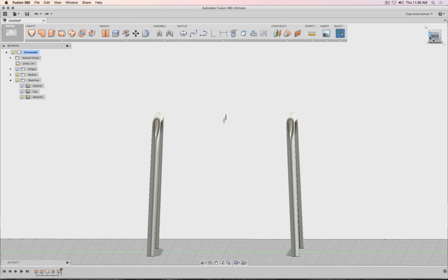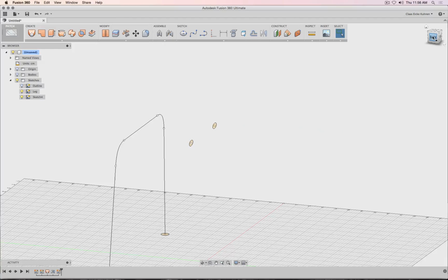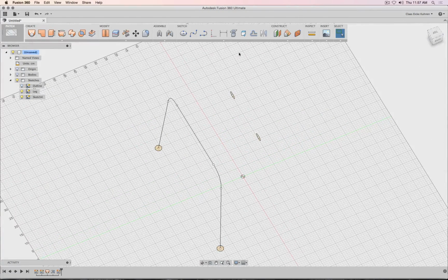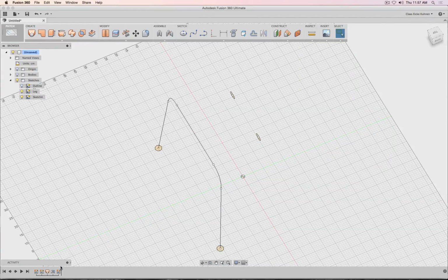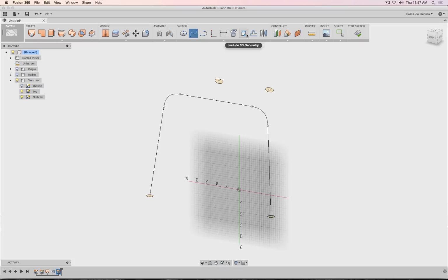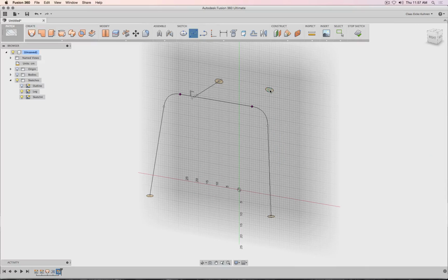So what we have to do is the following, and it's what I'm going to demonstrate to you. It's somewhat similar to the way Alias might work with 3D sketching. So I'm going to 3D include the line. Whoops. First I have to go into sketching there. I 3D include this line from my leg sketch. The main reason for that is now I can create a spline from this center point and snap onto this line. And then from this line, snap, and there. Perfect.